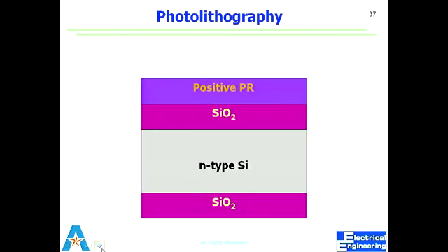So we know all this by common sense. These are all the parameters that go into that process. We want a specific thickness of resist, because it will depend on the dose of the light that I shine, and that thickness will define how deep that can be. We'll look at that. But these are all common sense things. So we apply this resist by that process where we apply a certain photoresist and spin it for a certain time at a certain RPM. That results in a certain thickness of resist.